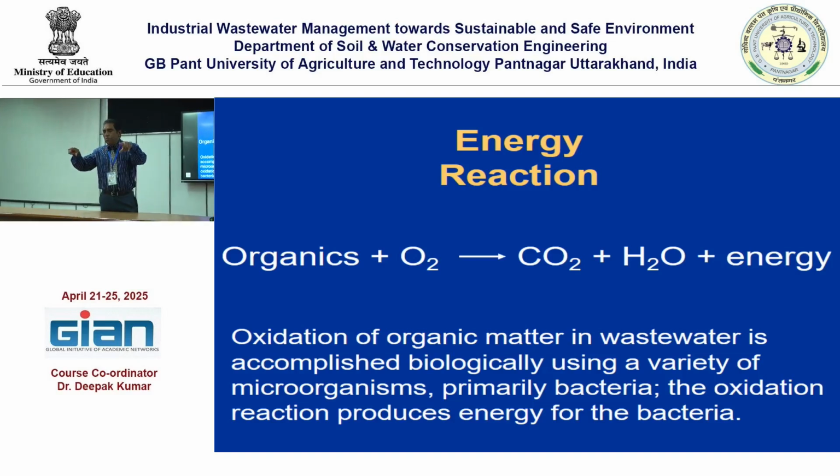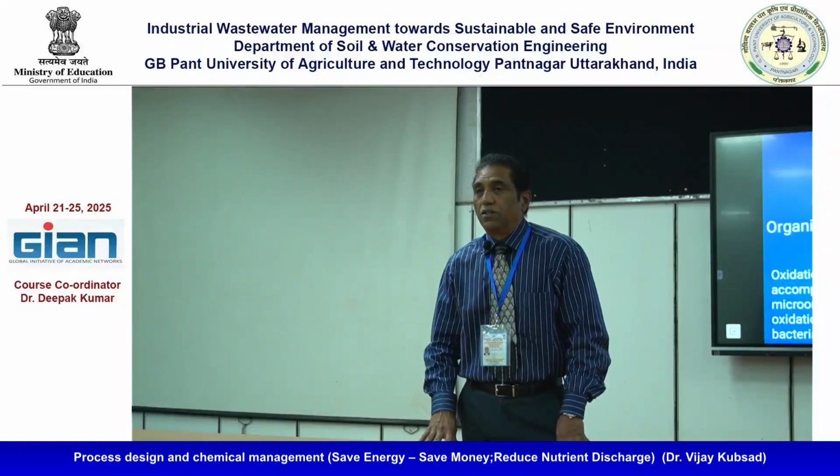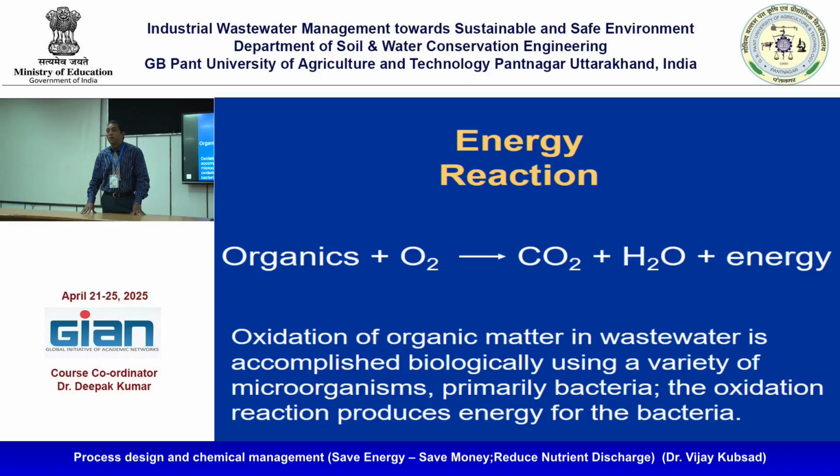It is not only what you saw yesterday, a concrete pond where you put aerators and then treat. If there is a seasonal plant, or if the volume is too high, 100 MLD or 1000 MLD, big plants, then you go for geomembrane. You can't do that. You do a double liner geomembrane with leak detection.